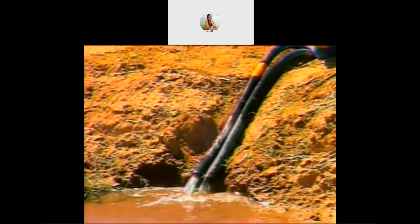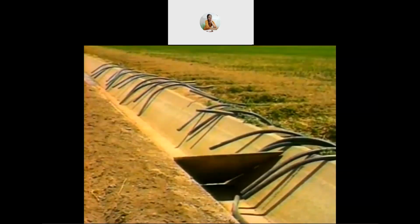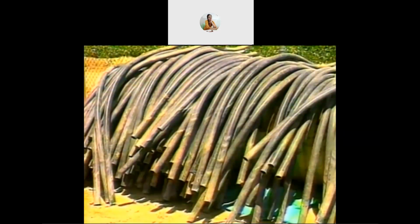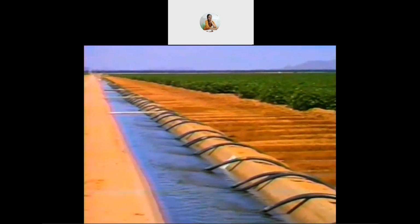Now that you know your fields, you should plan each irrigation before you irrigate. Before you start irrigating, you should know how many siphon tubes and boards or checks you will need to block the irrigation canal. You should also have extra siphon tubes on hand in case water isn't moving down some of the rows, or if more water is being delivered to your ditch than you planned for. How many siphon tubes per row? How many rows in each set, and how many sets to get across the field? How many hours for each set?